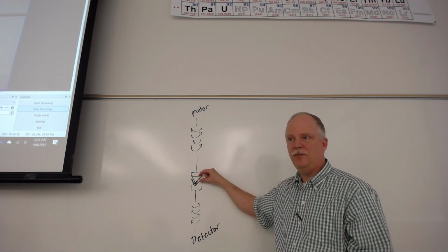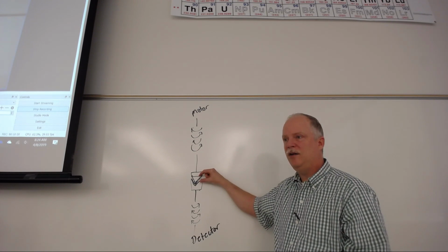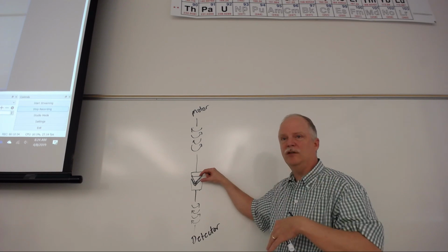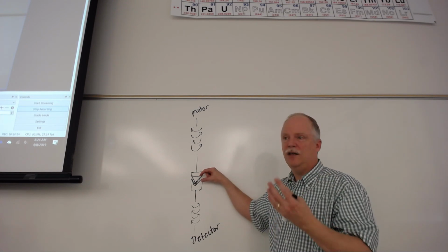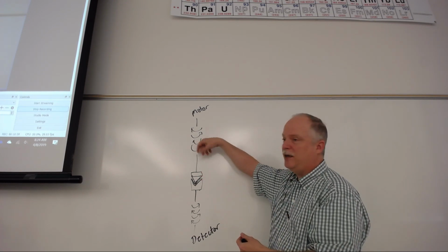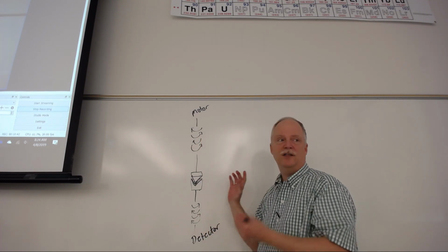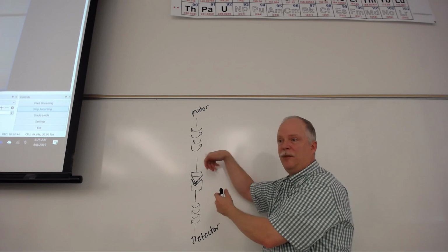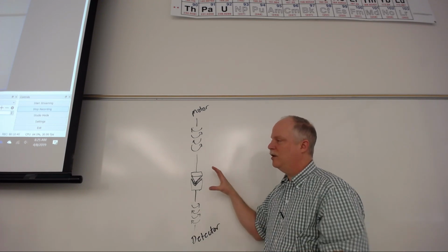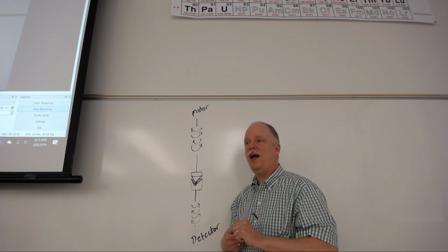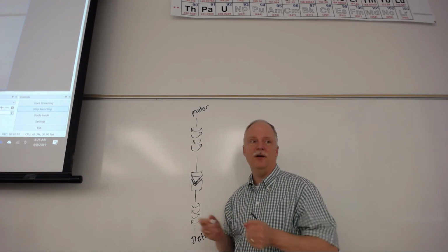And so that would be a low velocity gradient, which is a high viscosity, because the viscosity opposes the velocity gradient. And if this motor can spin freely and this one never turns, then you don't have very much viscosity at all, because they're slipping. And so this is one way of measuring these properties. The way we measure them in the lab is with the falling ball viscometer.